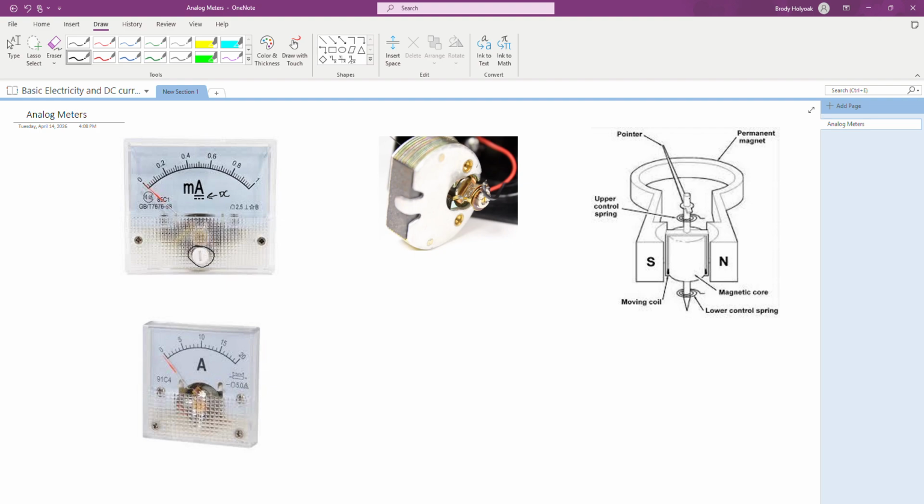It'll change the position. There's like a key in there somewhere, so it'll adjust where the shaft sits. And you can make it so that this pointer, with the natural magnetic field of what it has, is pointing at your 0 or your starting mark. And once you have that in, that's called a zero calibration, and that's making sure everything is working the way it should.